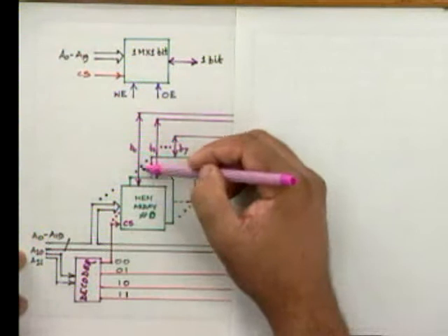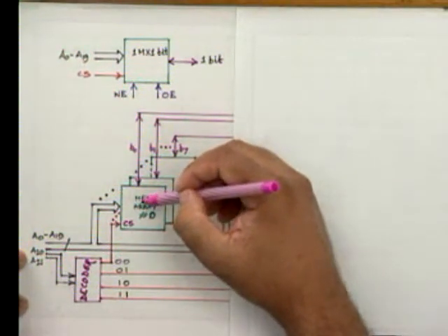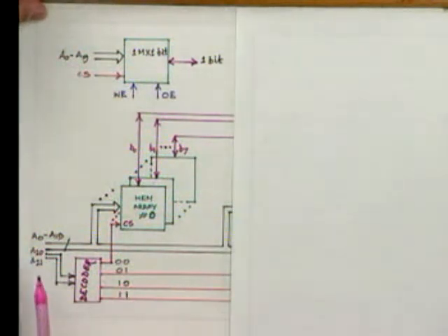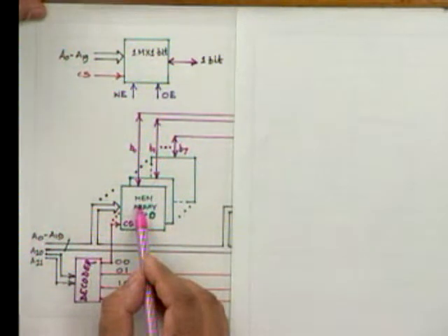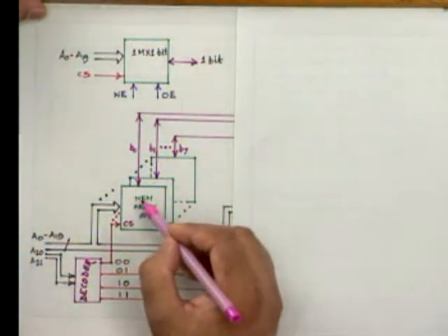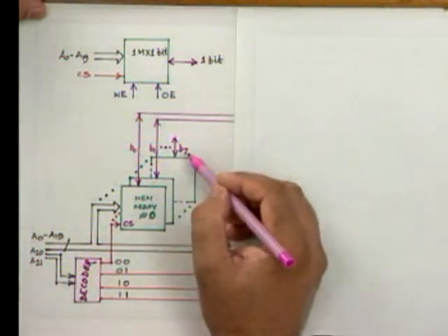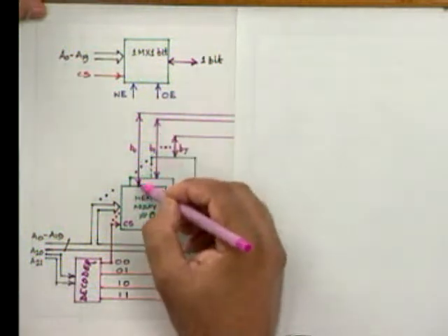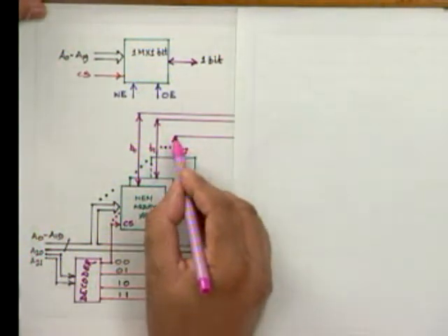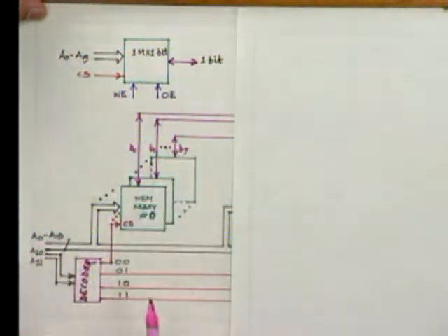output, in the case of a read, the content of the corresponding cells in each of these planes or in each of these chips, right? Let me repeat what I'm saying: depending upon A20 and A21, if it is 0, 0, then the entire stack is selected, right? Say I am reading. In that case, depending upon A0 to A19, one cell in the same positions in each of these planes, that means each of these cells, will be outputted through these lines. The first one will come to B0, the second one will come to B1, and similarly the eighth one will come to, say, B7, right? This will now come to the data bus.